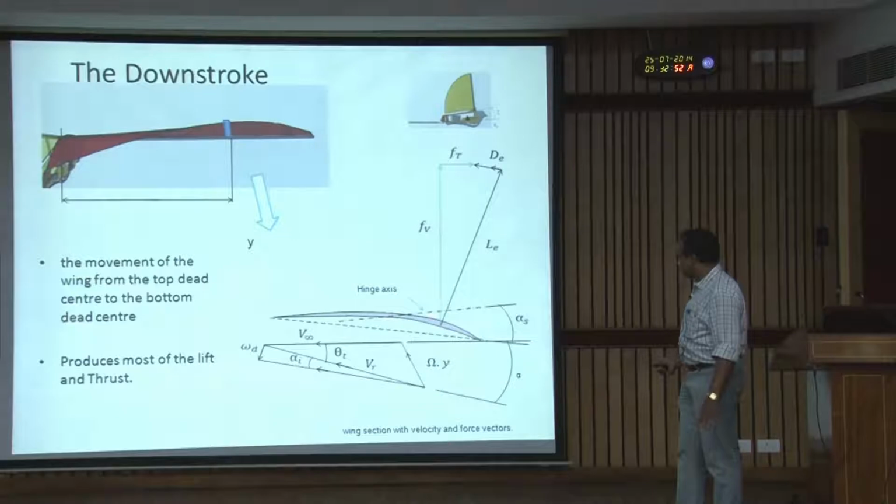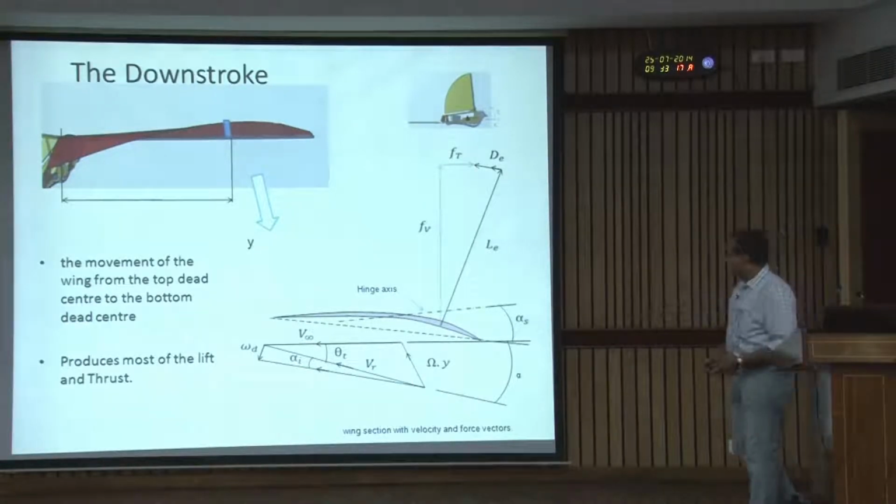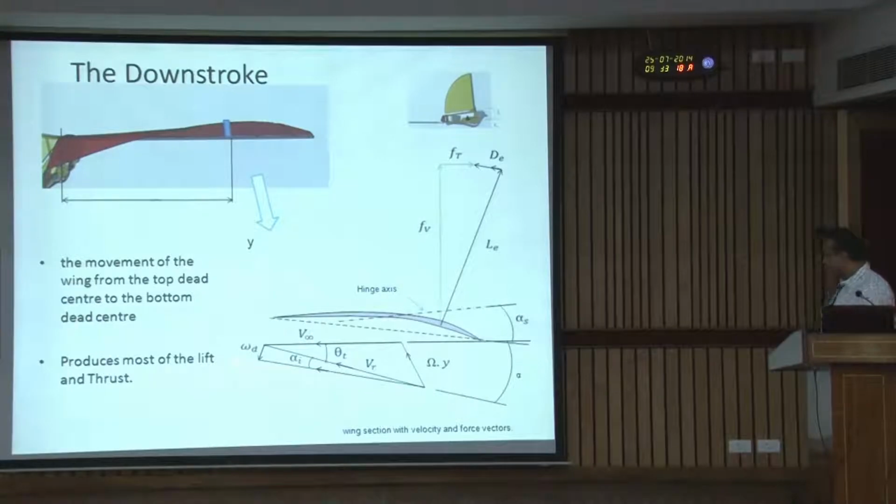This is probably the very elementary level theory, which we have upgraded now, but I am not showing it here. If you take any section from the root, it will be like an aerofoil shape, and it can have an angle, that I showed as the thrust angle, with respect to the hinge axis. There will be some angle of attack, because omega_y is the flapping component of the velocity. So, there will be a relative velocity.